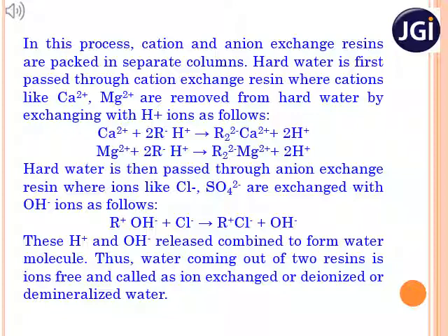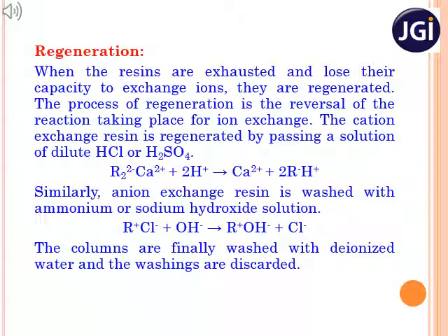Now, the water is free from all types of hardness causing ions and hence it is called deionized water or ion exchanged water. But after prolonged usage, the resins will lose their capacity to exchange the ions. Therefore, they are to be regenerated or reactivated. This can be done by following a procedure which is exactly opposite to that of ion exchange procedure described above.